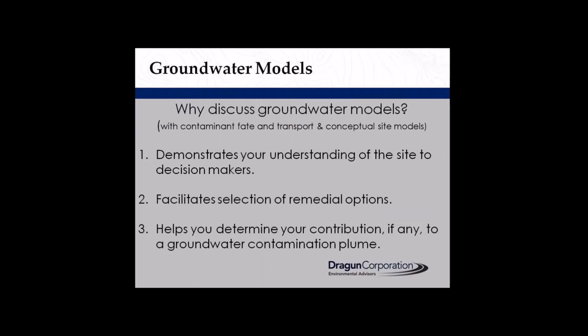So why discuss groundwater models? And in small brackets there, I've got the contaminant fate and transport that we talked about before, and conceptual site models that we talked about before. Well, groundwater models help to demonstrate that you understand the site that you're dealing with, and that makes decision makers more comfortable with what you're saying. Models also help to facilitate selection of remedial options, and they'll help you to determine your contribution, if any, to a groundwater contamination plume. So if there's multiple contributors, it's a good tool for helping you figure out what your responsibility is.